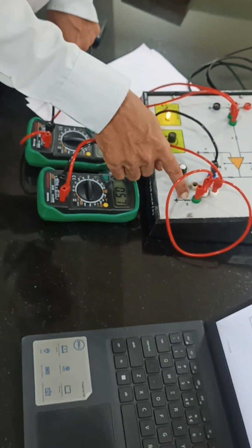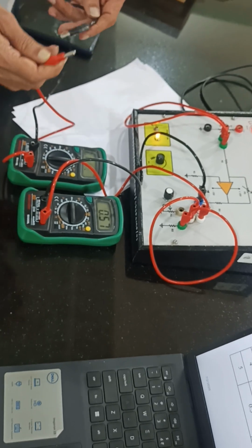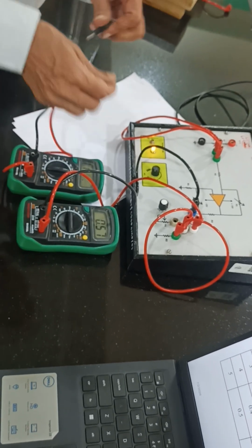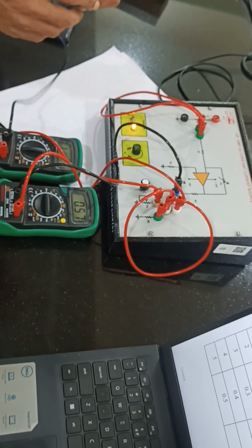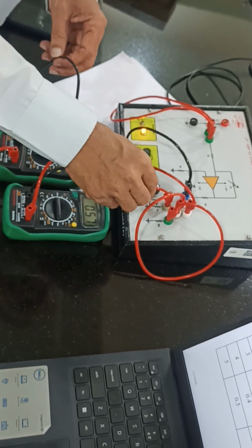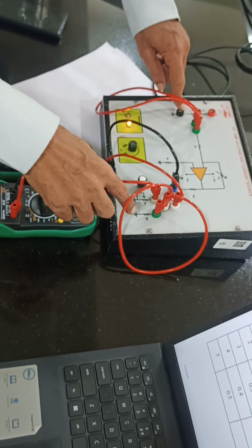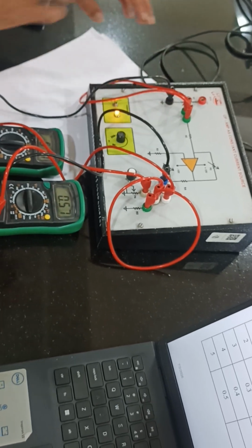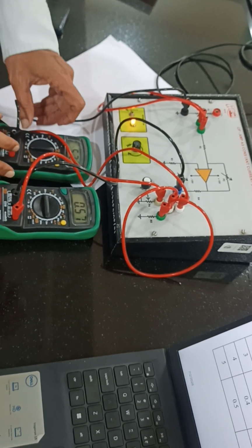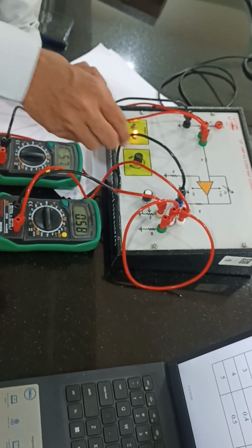Now how to measure the resistance? See, this is a fixed resistor and this is the variable resistor. I am interested in the variable resistor. So how to do the connections? I will insert the red wire here and the black wire has to be inserted to ground, but ground is here and the potential at this and this point, they are zero only. So this is also a ground terminal. Now here you can see that there is some value of this resistance, that means 57 ohm.